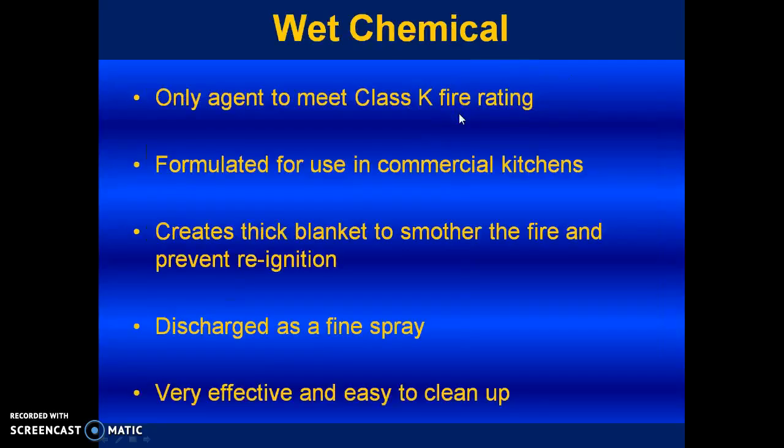Wet chemical, this is the only agent that will meet your Class K fires. This is obviously formulated to use in commercial kitchens, creates a thick blanket to smother the fire and prevent reignition. It discharges as a very fine spray, and it's effective and very easy to clean up. You guys really won't be dealing with any of this, just be more or less cognizant and aware that it's there.